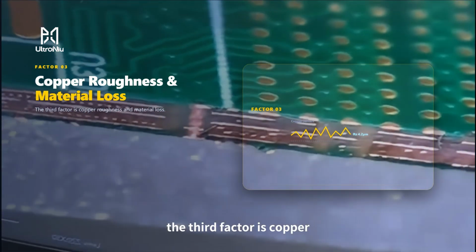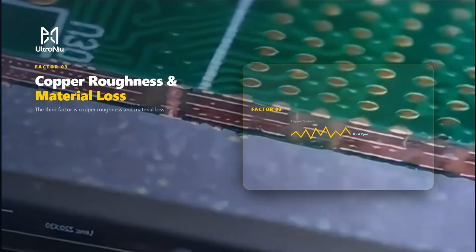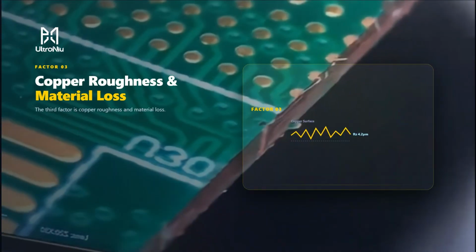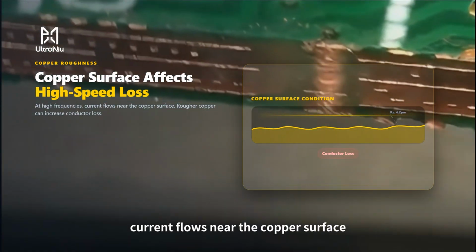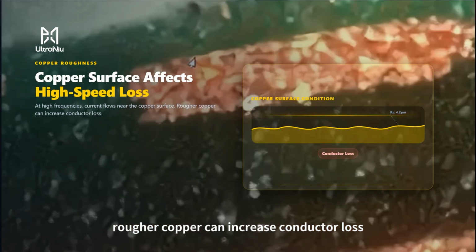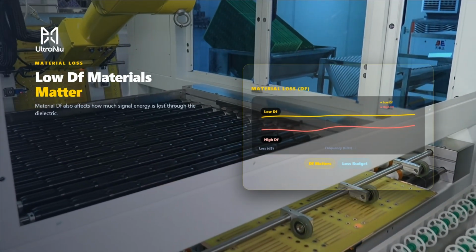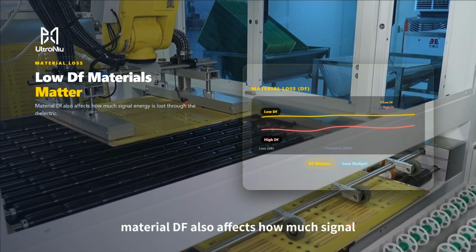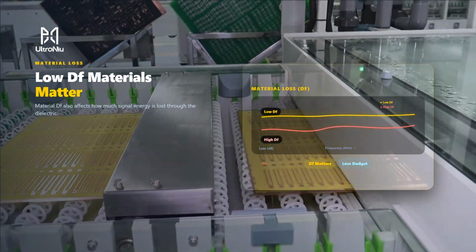The third factor is copper roughness and material loss. At high frequencies, current flows near the copper surface. Rougher copper can increase conductor loss. Material DF also affects how much signal energy is lost through the dielectric.